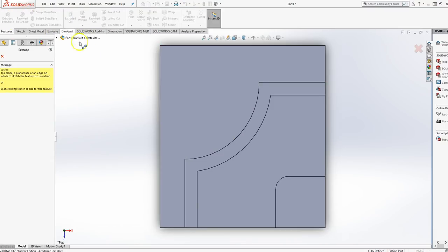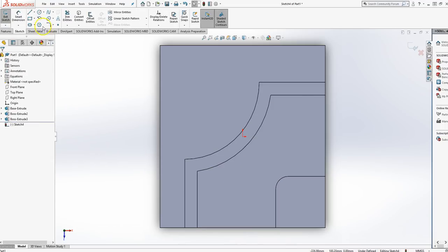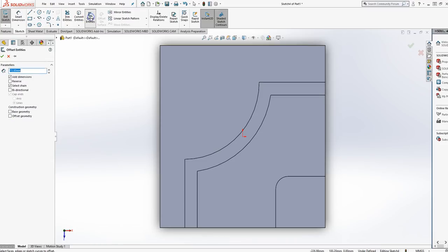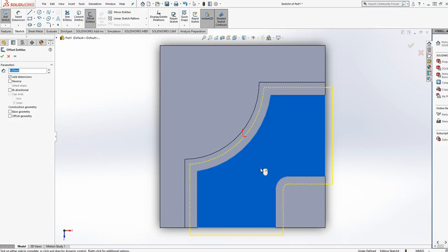Well, we're going to use an extrude cut this time because we're going to cut the channel in this surface. I'm going to use offset, and I'm going to change it to 9. Select change should be available. I'm going to click in the inside of this. You notice everything here highlighted orange. If I do that, it's going to grab everything.